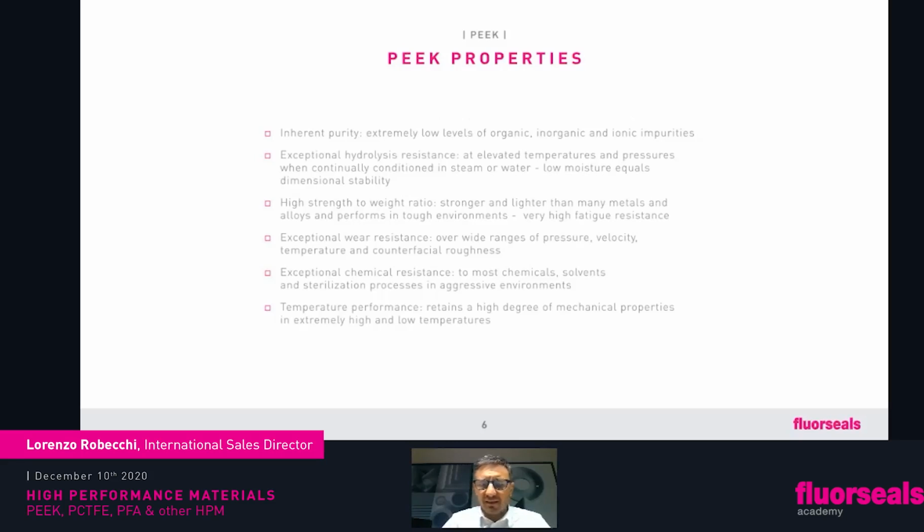Chemical resistance, well, we know that PTFE is not a king, it's the emperor of chemical resistance, so there is no plastic like PTFE. All fluoropolymers are at the very high end, but just a step beneath is PEEK. Again, among all plastics, PEEK has a terrific chemical resistance. Temperature performance, we already saw, goes up to 250, but also for cryogenic application, we're going to have a quick look later on.